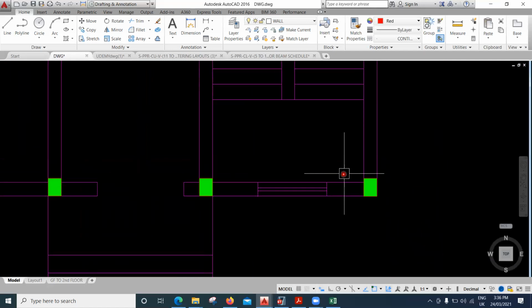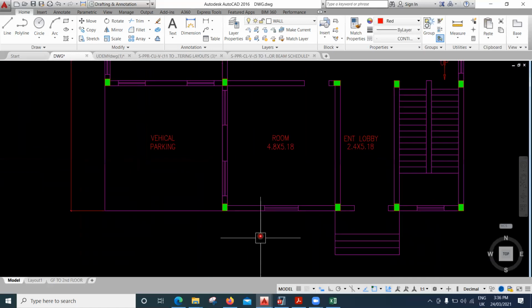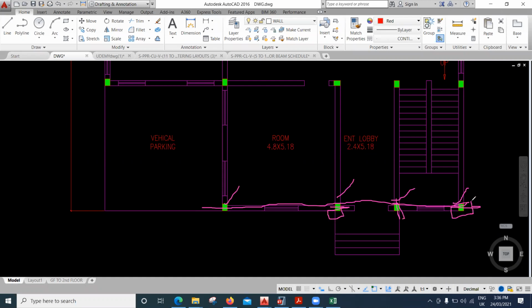But as far as possible, try to orient in one direction. What I'm trying to tell is, whenever you place a column, make sure at one particular line, your column is in the same direction. Now here it is vertical, here also vertical, here also vertical, here also vertical. So it's a good way of doing it. Don't try to do something like this, vertical, then one horizontal, then another vertical, and then another horizontal. Don't do that unless there is a need for it. If we have a chance to keep everything at the same orientation, either vertical or horizontal, try to do that.